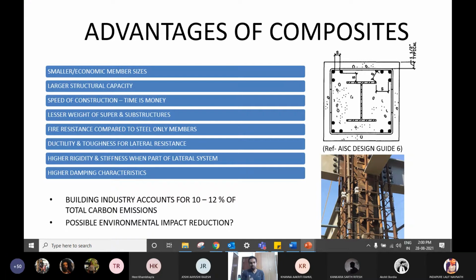Yes, you want to build something with steel. With steel, what happens is it is susceptible to fire. When fire hits it at a temperature enough to cause some damage, it's going to collapse. We'll look at a case later, what happened to one of an important building, how it collapsed. But the thing is, steel structures need protection from fire. Now, in these composite sections that we are looking at right now, the steel is surrounded by concrete, and that serves the purpose. Okay, so that is taken care of.